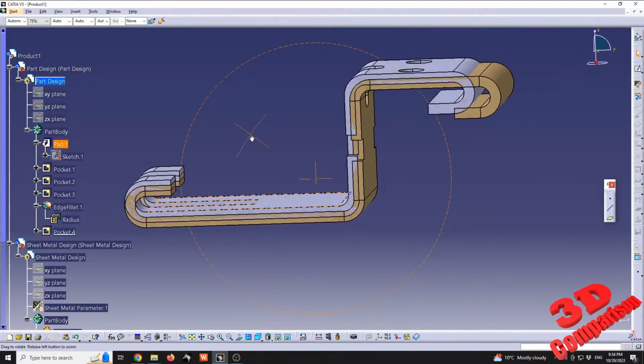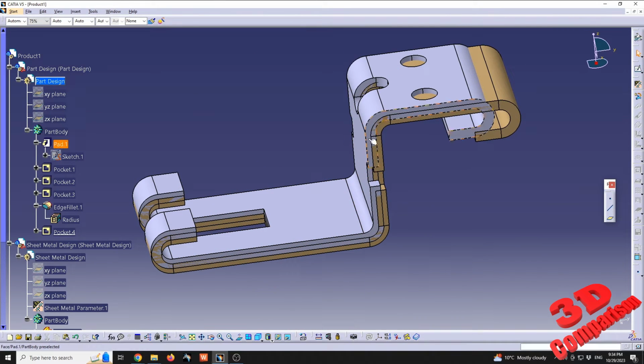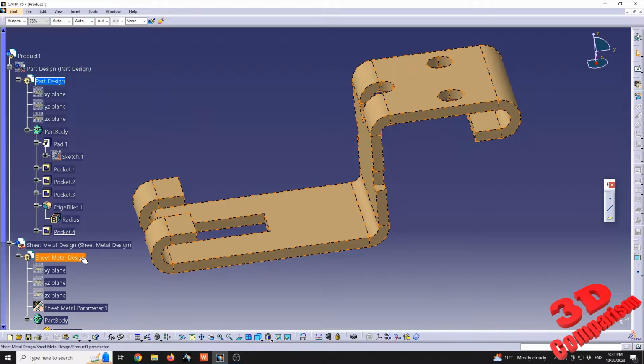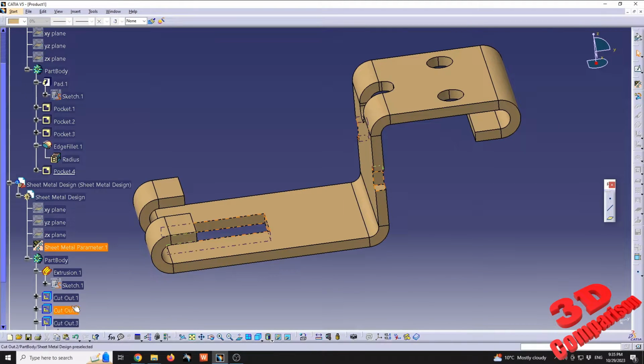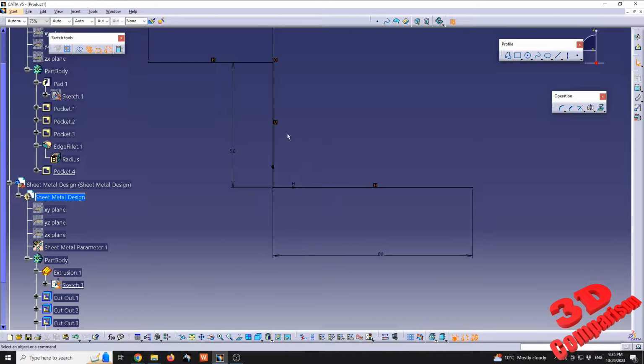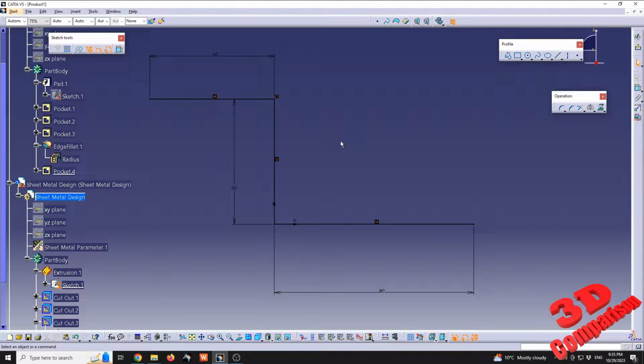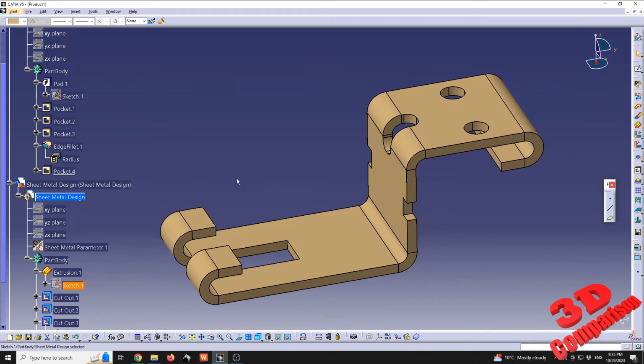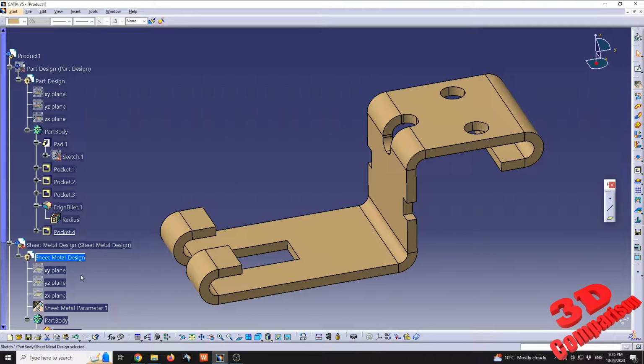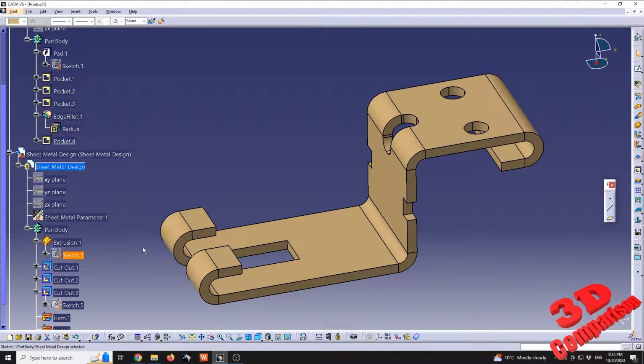As you can see, there are also some differences regarding the offset side where we added that material thickness. So it is really convenient to work directly with sheet metal design, where you're just gonna have a single sketch controlling everything, and after that you don't have to think about the offset value, if it should go at the top or at the bottom. As you can see, you can easily change that over here. It's much more easy and convenient.